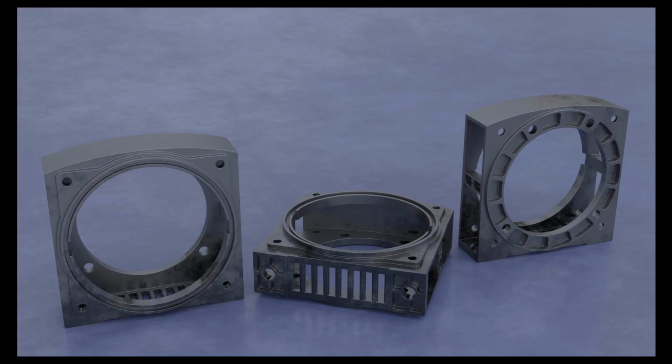So these are the most important things when you do an N-gon model like this. We're not too concerned with topology, but even though N-gon modeling can be easier to create complex looking shapes like this, it's not like you can get away with anything. Even though we're not going to pay too much attention to the topology, we still have to look out for certain things, and I will create a reasonably clean mesh that makes sense.